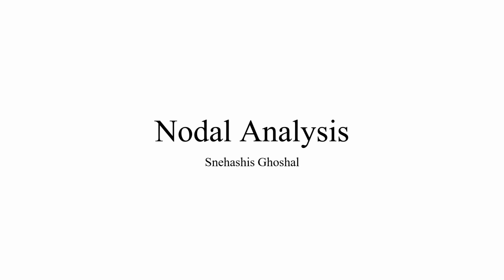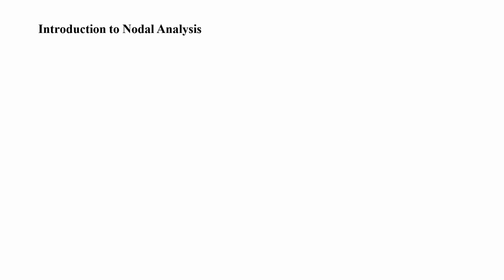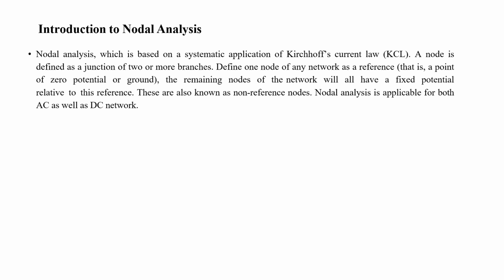Hello. In this video, we are going to discuss one network solving tool, that is nodal analysis. Although our discussion will be confined here to DC circuits, the concept is equally applicable for any AC network. Only the resistances are replaced by impedances, and the source magnitudes become periodic, sinusoidal for the AC analysis. Nodal analysis is based on systematic application of KCL and Ohm's law.